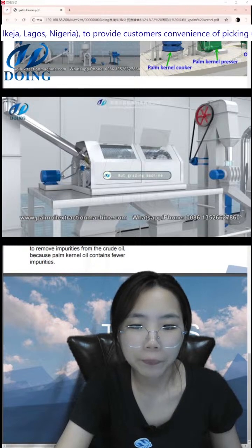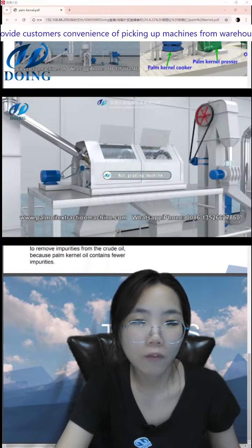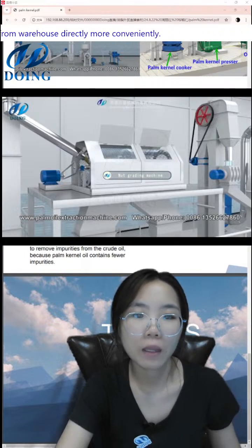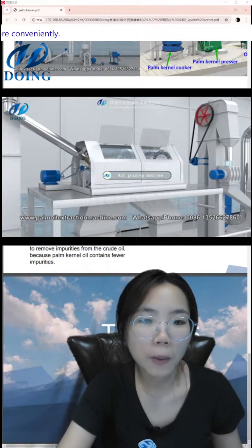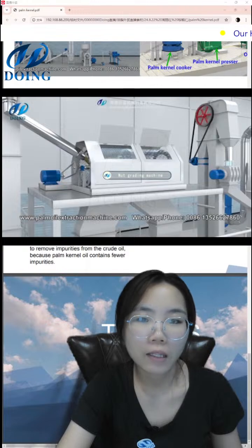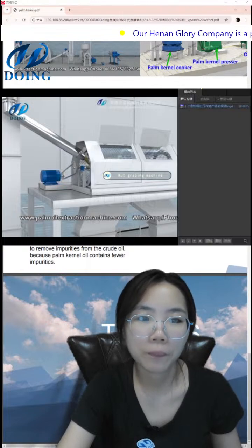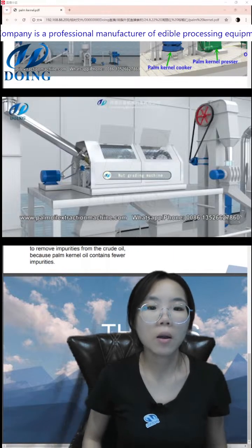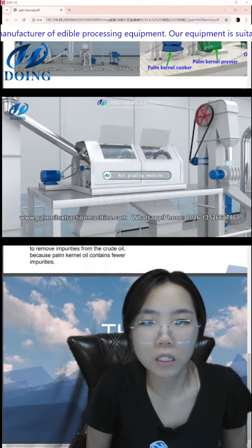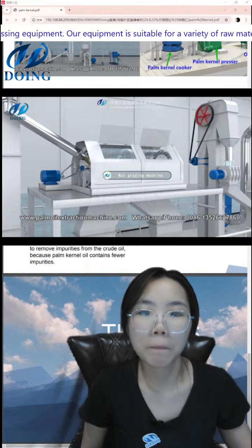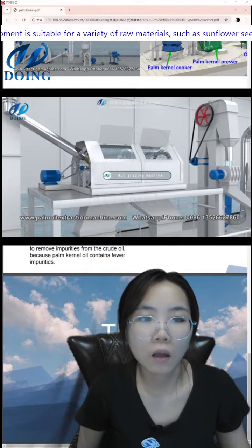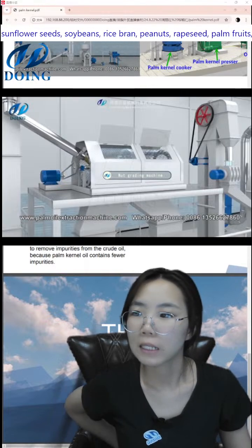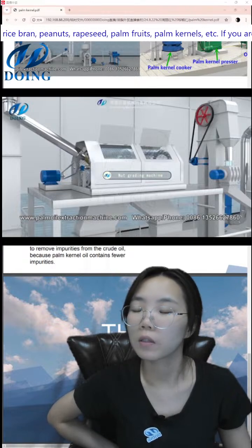The palm nuts are classified by size into two cracking machines, and the palm nuts in the same shell machine have a smaller size range, avoiding the situation where small palm nuts cannot be cracked, or the kernel of bigger palm nuts is broken or cracked incompletely. And this is the foundation of this machine.